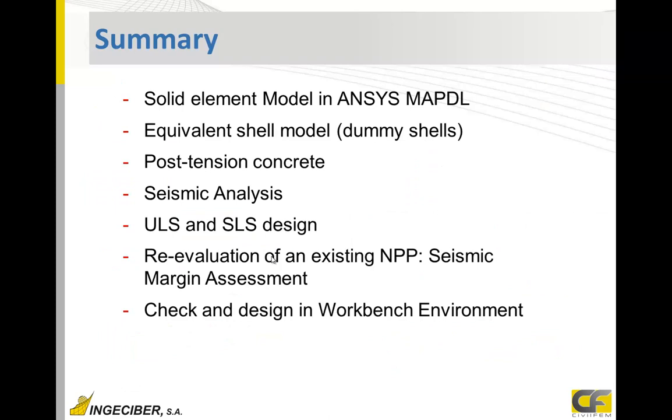And as a summary, you can see that in a solid element model in ANSYS, we can obtain the equivalent shell model, apply post-tension loads, seismic analysis, and design by code, and also perform a seismic margin assessment in an existing nuclear power plant.